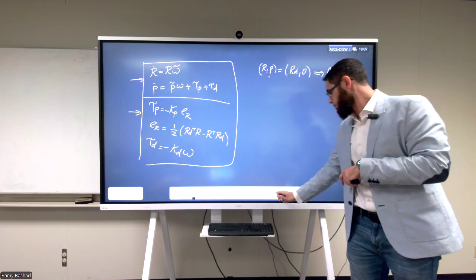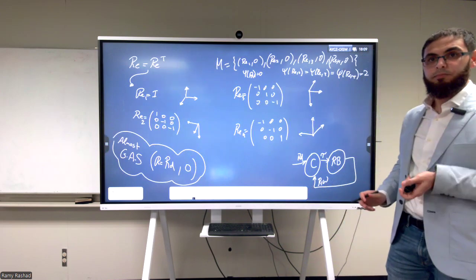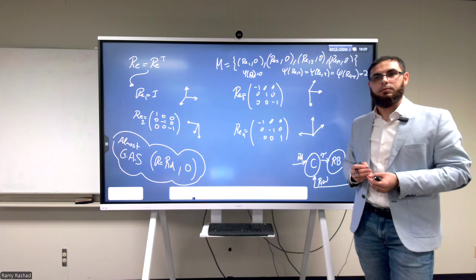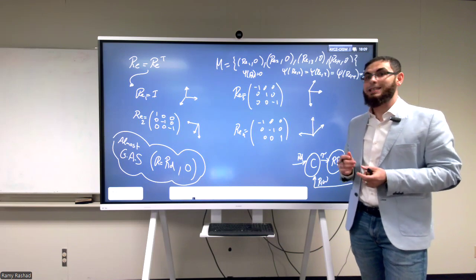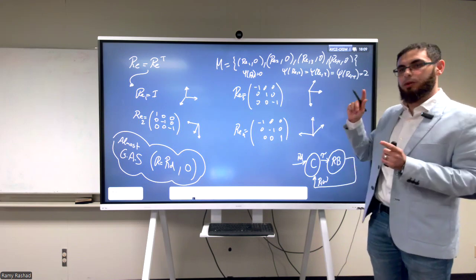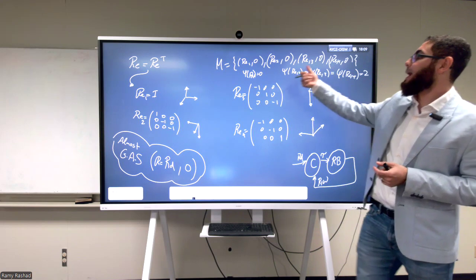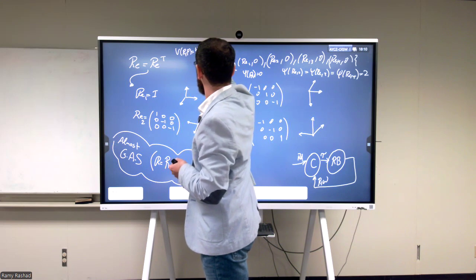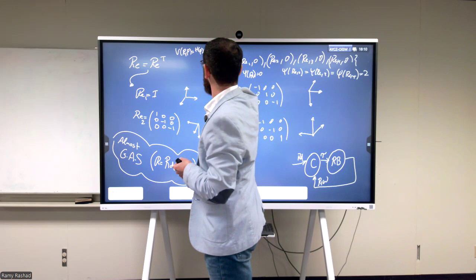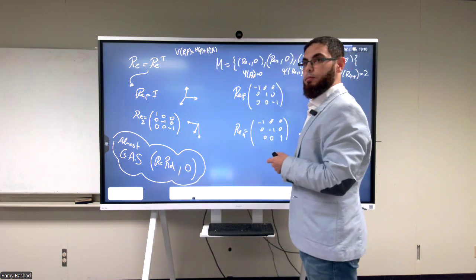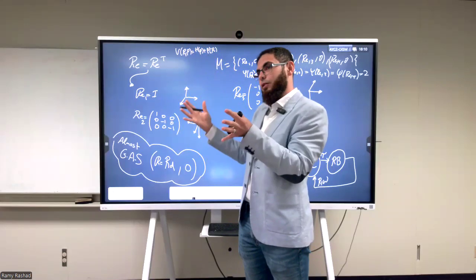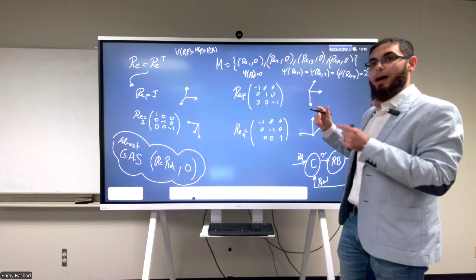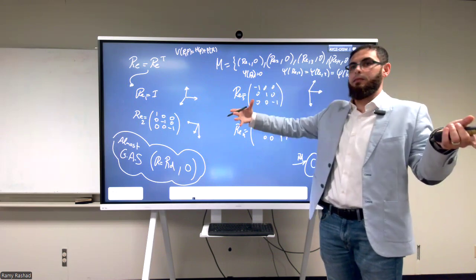It should be asymptotically stable. It should be locally positive. So what we did here by excluding the 2 is that now we have the Lyapunov function, which is given by h of p plus psi of p, psi of r. Here I chose the values of psi of r less than 2. So I only look at the values that have psi of r less than 2. So it's not the whole state space, and the only points I excluded by doing that are these 3 equilibrium points. So this region I'm looking at has all of the state space except these 3 equilibrium points.